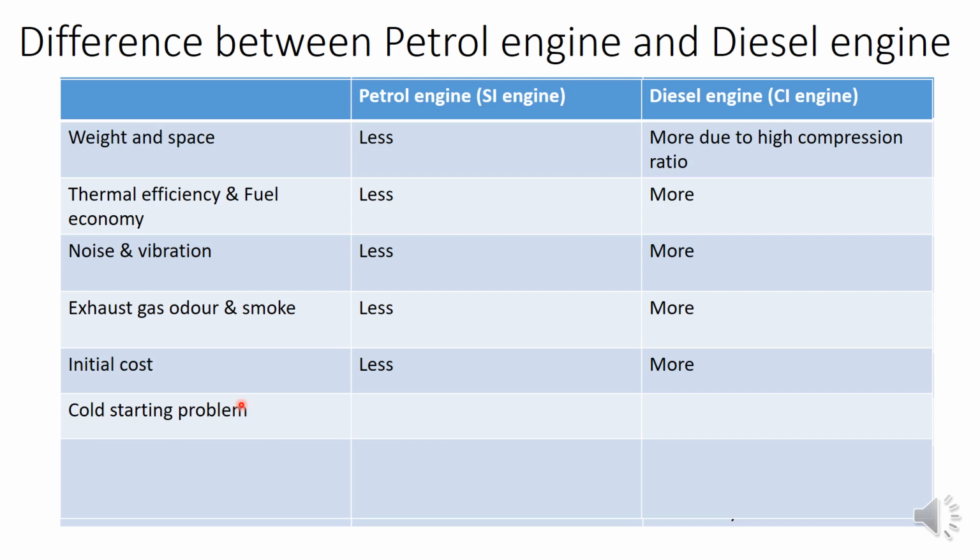It is lesser for a petrol engine, mainly because in a petrol engine the air and fuel are mixed during the suction stroke itself and used later, but in diesel only air is compressed initially, and fuel comes in the later stage. So the cold starting problem will be more for diesel.